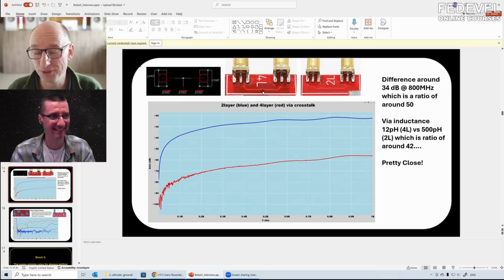Yeah, so one nice thing you could do, if you say, okay, with the 4-layer, a via has 12 picohenries in my case, because it's 200 microns of dielectric distance. If you cluster 4 of them together, then you would get a quarter of that, which would be 3 picohenries. So you could make a big improvement by clustering a bunch of vias together and thereby reducing the inductance. You're also reducing the DC resistance by a factor of 4, of course. But for high frequency, the inductance would be the biggest difference. And you should be able to, in theory, gain another 12 dB here. Let me see, you go from 3 to 4 times more. Yeah, it should be 12 dB if it follows exactly these rules.